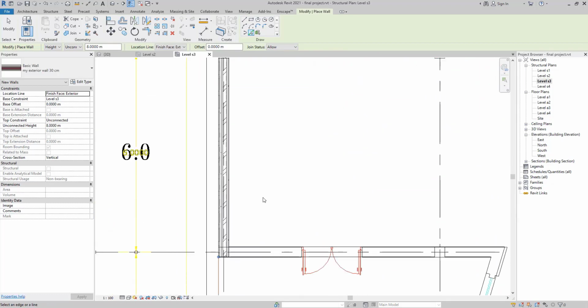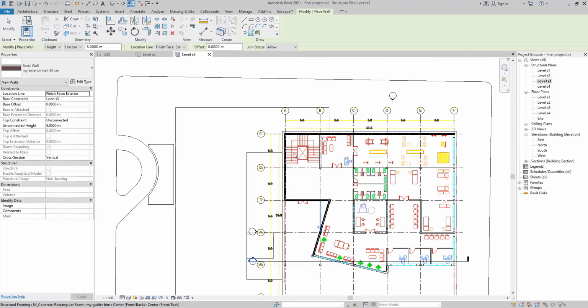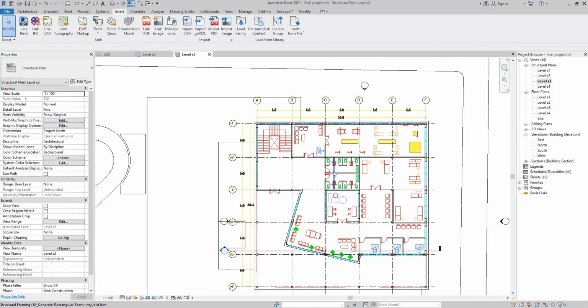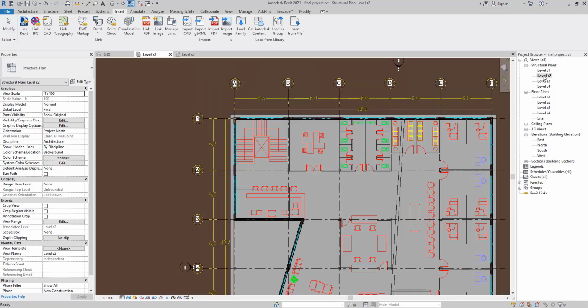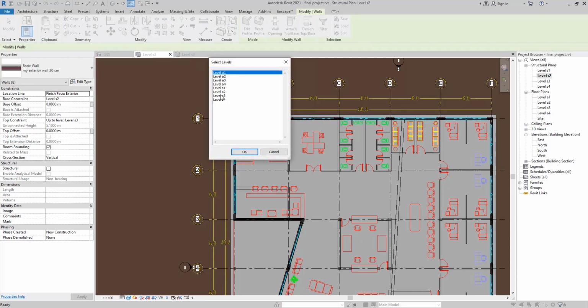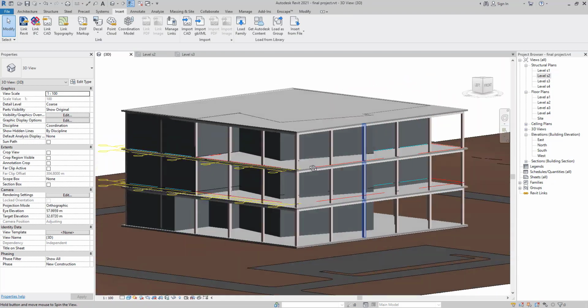Here we go. So we just start drawing and drafting our wall, and actually instead of drafting your wall separately, you can also use the copy tool and copy your wall, because the exterior wall is alright, all of them are the same from the second floor to the third floor. So you can just come here, select all of them, go to the copy tool and align to selected level. Very easy. You can go choose your S and then OK. Here we go. Our wall is from base level 3 and top level is 4. Let's check it out, and everything looks alright.